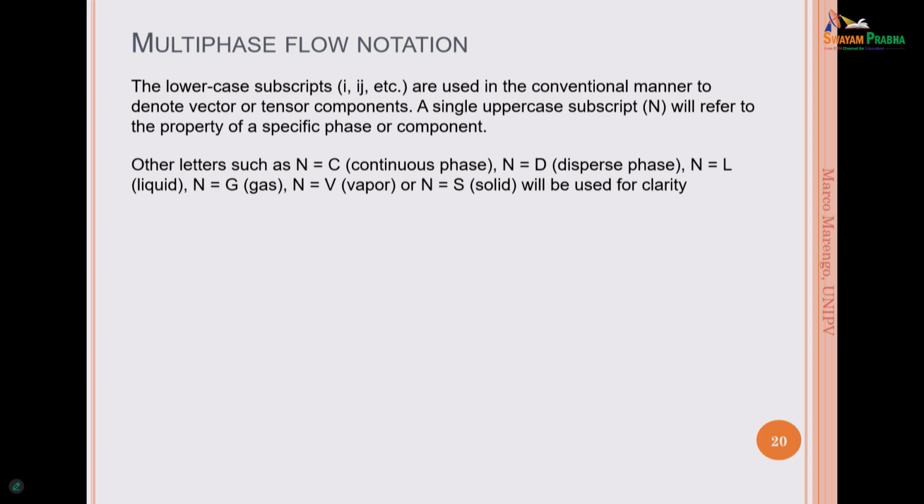If you are doing Euler simulations, you need enough droplets or bubbles to have an average property which is constant inside the mesh size. But this is again not obvious for other conditions. So this reflection is important as a consequence for the numerical simulations.